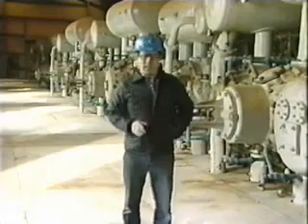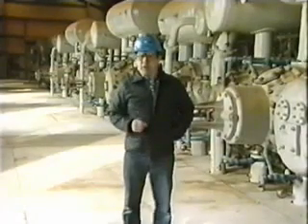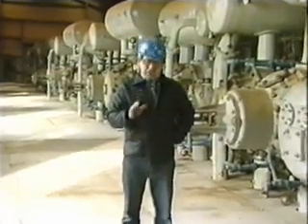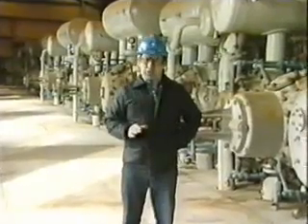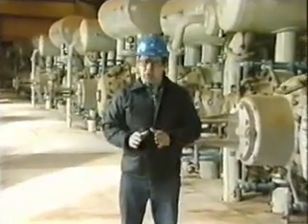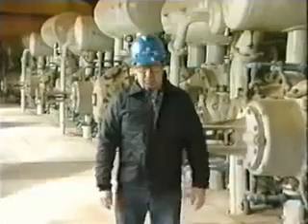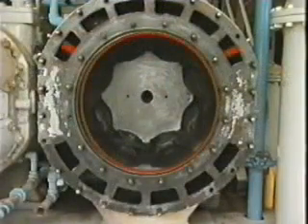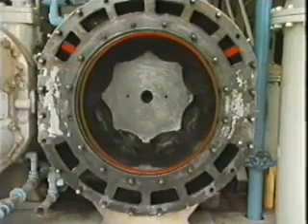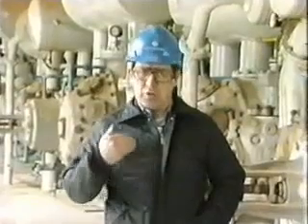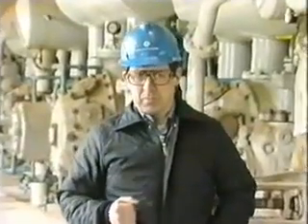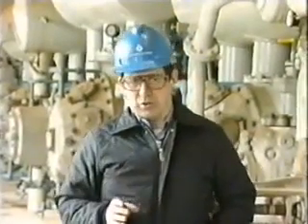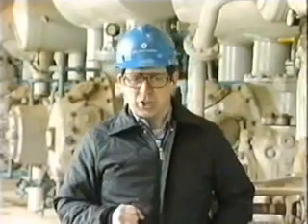Keeping things cool is vitally important in operating a reciprocating compressor, because excessive heat buildup can damage equipment, resulting in lost revenue and costly repairs. So, in addition to cooling passages, most compressors have lubricant added in the cylinder walls to reduce wear from the friction generated by the back and forth motion of the piston. Now, other compressors use special material, for example Teflon, to reduce friction.